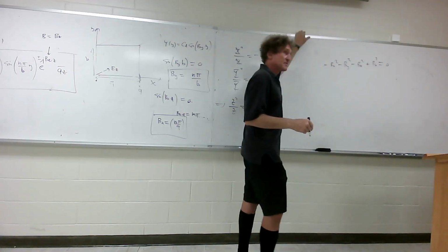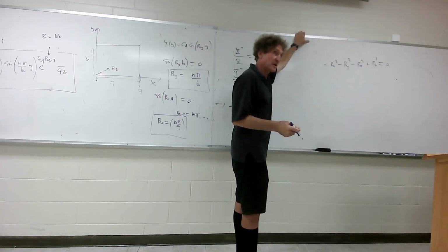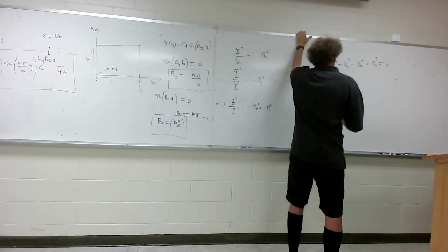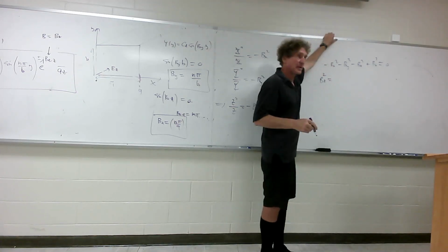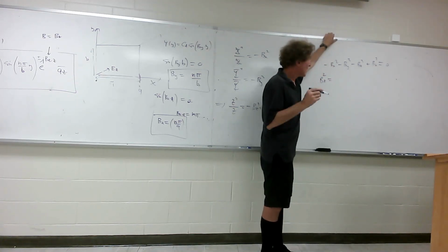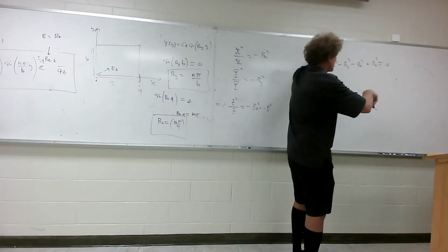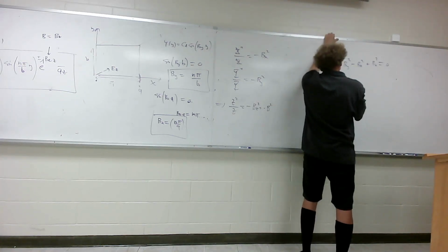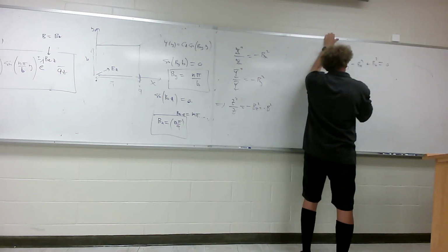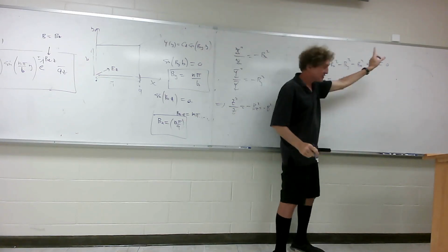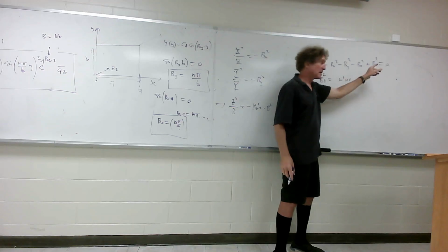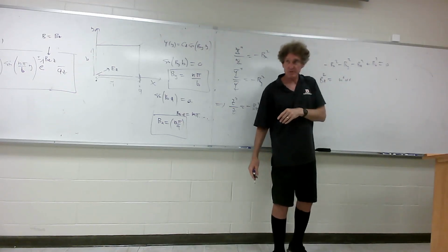Now I'm going to put the values in terms of omega. You with me, class? This is real important here. So now I can say, well, beta z, because that's the one I'm after, beta z squared is equal to, just follow me, beta z I'm going to take to the other side. So it is equal to beta unguided, which is omega squared times mu epsilon. That's this one. I'm taking beta z to the other side. So I've got beta unguided is just omega squared mu epsilon.